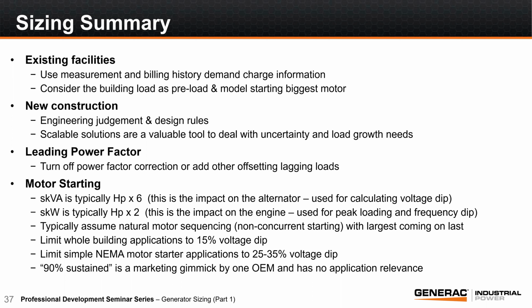Also, in some of the higher altitude or colder environments, people will blend their diesel fuel with kerosene, right, to get a lower freezing point or cloud point within that fuel. And when you do that, you're also using a fuel that does not have the BTUs of diesel. And so you would be derating by maybe up to 5%. I know that's what happens in the colder climates during the year, they have heating oil, and that heating oil they use as the kerosene. They cut the diesel with the kerosene, and they're going to lose the potency because it's not quite as powerful a fuel. So those are a couple other things to think about: what fuel are you using, and making sure that it's a good quality fuel that's going to give you the output that you're looking for. That's a good point.